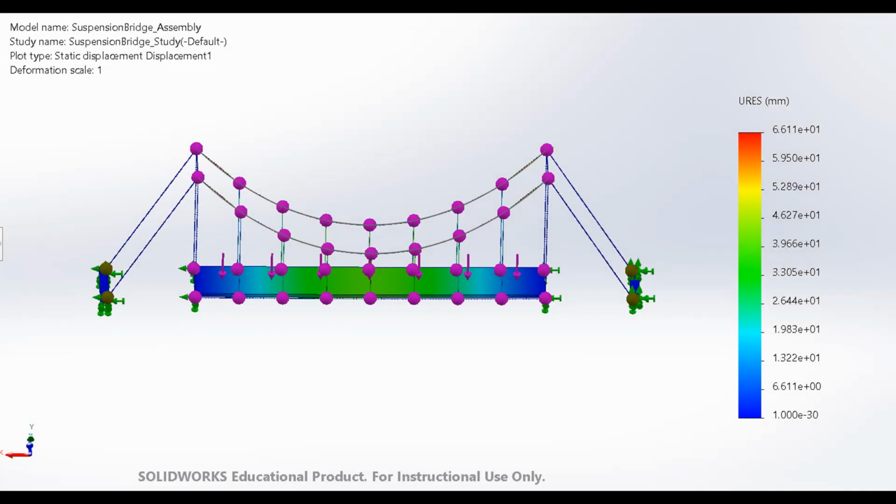Finally, let us look at the suspension bridge. It is a very light structure, approximately 1,500 kilograms, but unfortunately this structure was too flexible for this short span. It's not seen here, but the maximum displacement is about 66 millimeters. So this teaches us that a bridge can meet strength requirements, yet fail serviceability requirements.